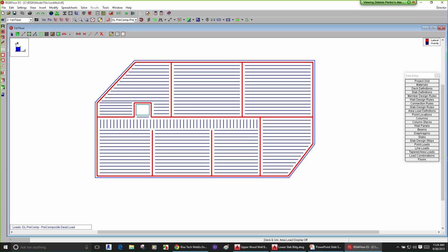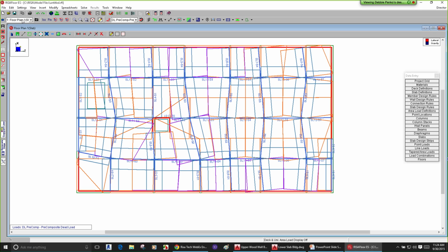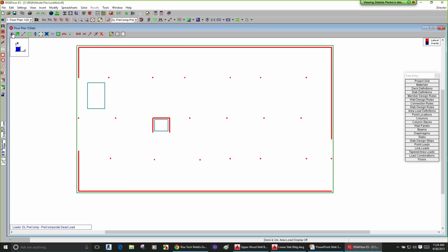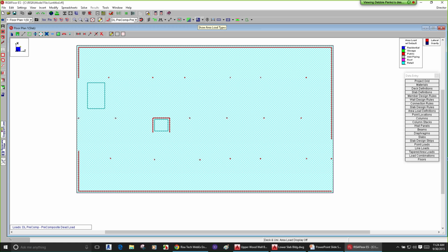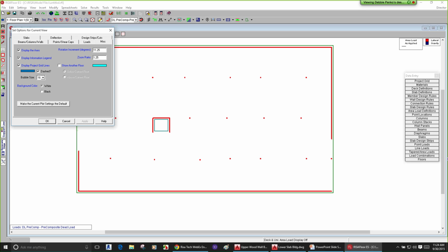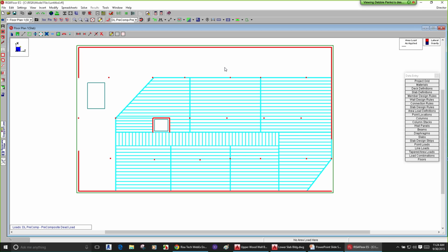Okay, so I've got all of that in place. The last thing we can do before we move on is go down to that lower floor and take a look. I'm going to turn off this here. Let's see what's going on this floor. We said we had a default area load on this structure of retail. But where the structure isn't sitting on top of it, where we can put the floor on top, that's actually going to be like our roof area. We have retail inside of that area, but where people can walk out onto that roof area, it can be multi-use.